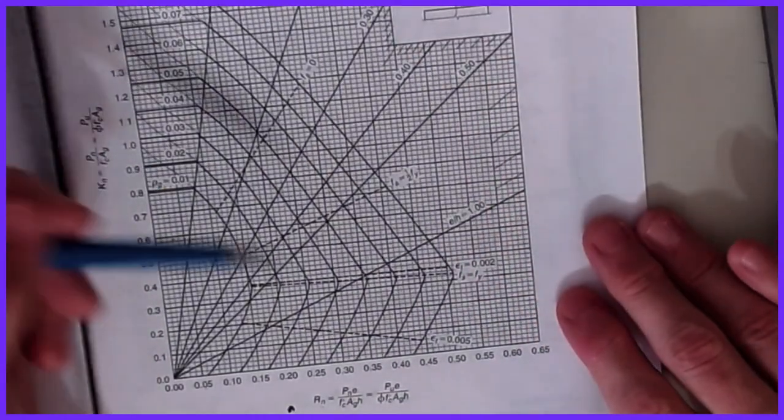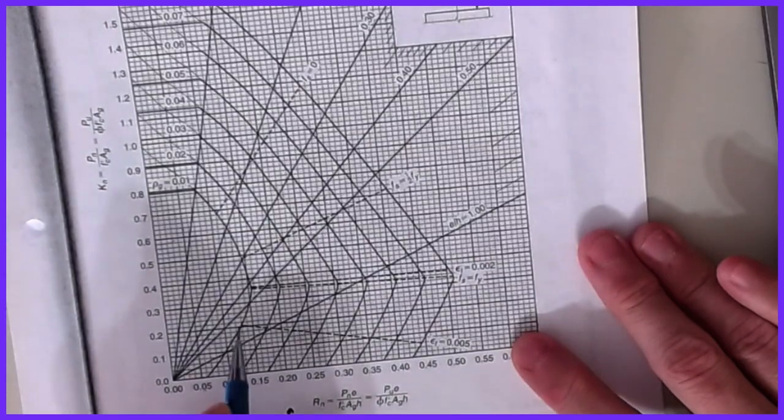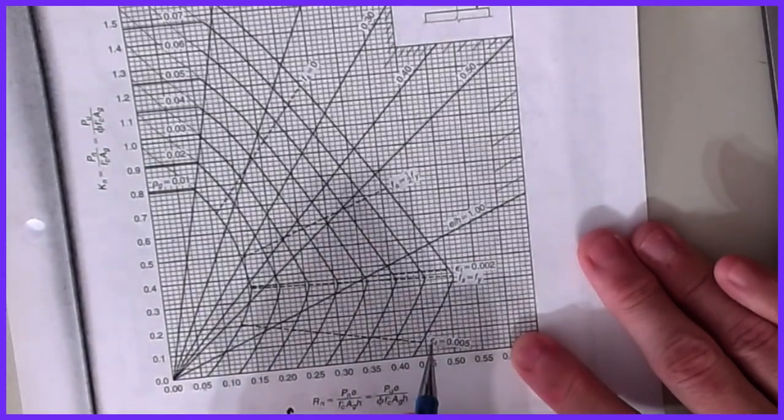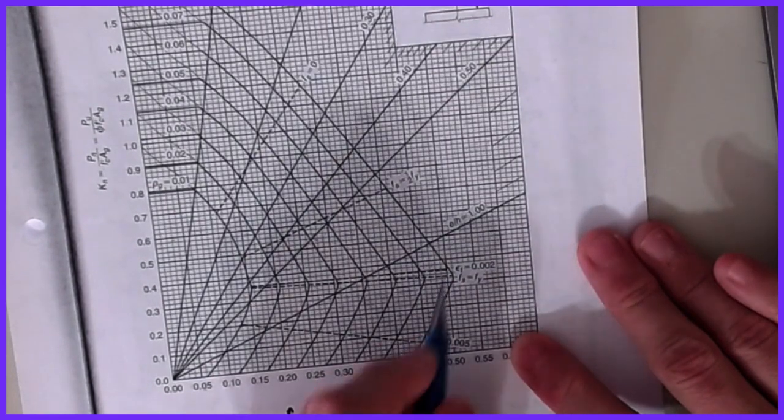Okay, now, some other information that's kind of hidden on a lot of these charts that's kind of interesting is, for all of these row values, this line right here represents the epsilon T, the tensile strain of 0.005. So if I'm below that line, my phi for bending is 0.9. And then if we look at the other lines, anything above this, you know that phi is going to change based on the yield strain.